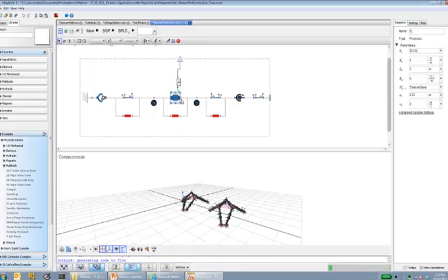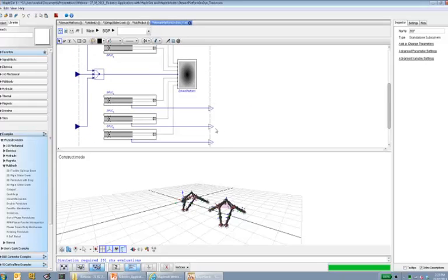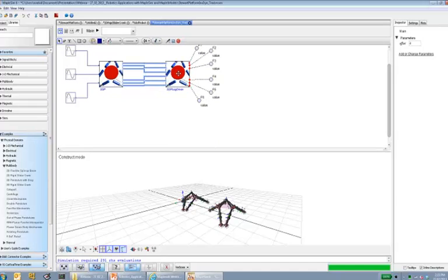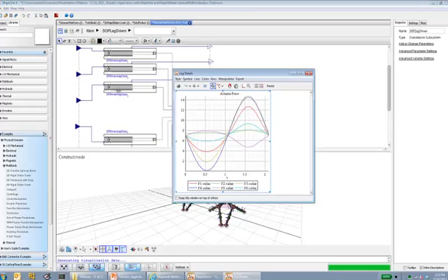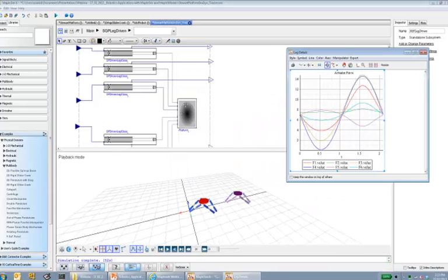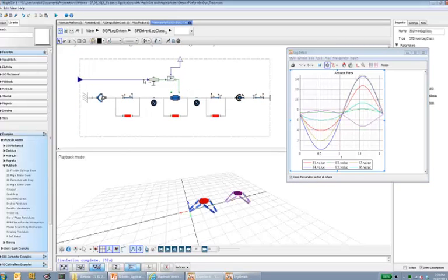And that extension can be measured via a sensor, and that sensor will give us the value we need, and we collect those values, as you can see here, from all of the 6 legs, and we provide them to another Stewart platform model. The difference between this one and the previous one is that instead of moving the platform, we are moving each leg according to the value that we have just calculated.